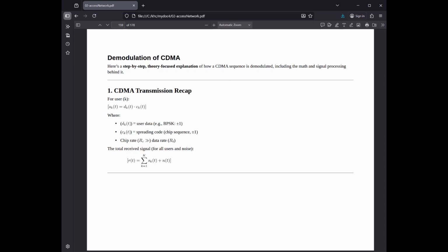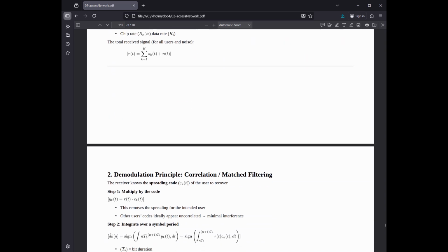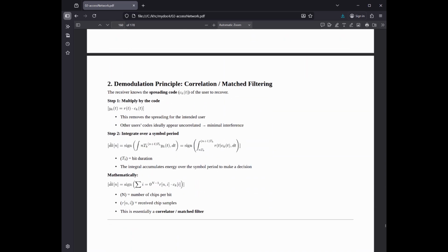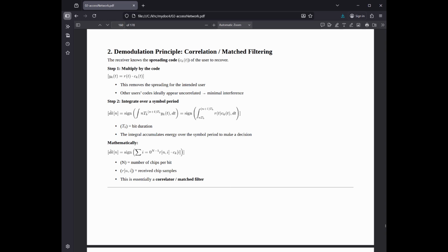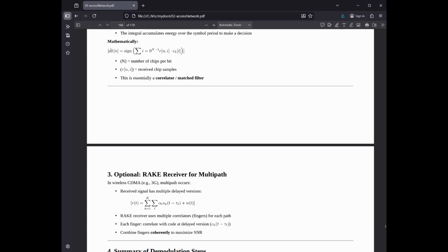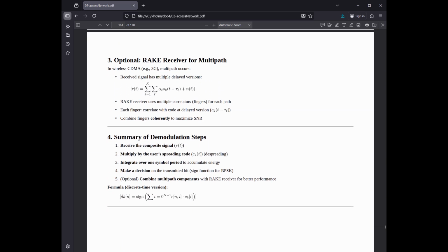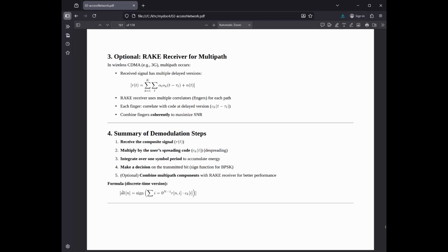1. The received signal model at the receiver antenna. The signal is a summation of all active users in that frequency band, plus channel noise. Mathematically, for K users, the baseband received signal includes: the amplitude, power, of each user; the actual data bits of each user; the unique spreading code, chips, of each user; and additive white Gaussian noise, AWGN.